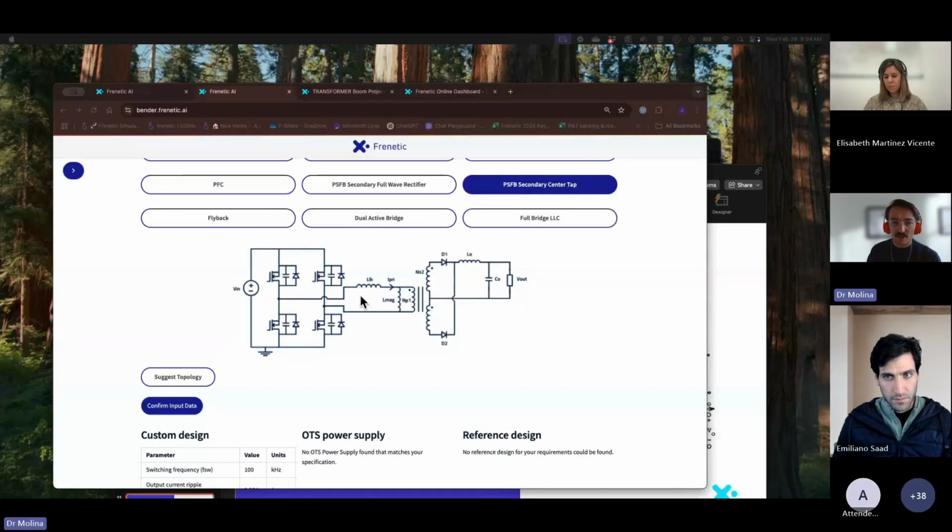So the capacitor that you see here, basically when you are discharging these capacitors, or let's say when you made an equivalent model, the capacitor that you will see here and you also need to consider is the capacitor of the transformer that you will find if you measure from here to here, the transformer.